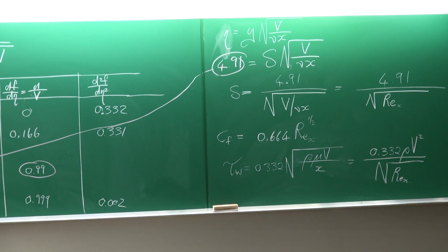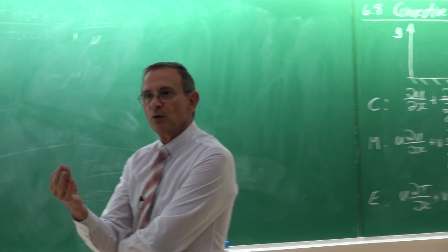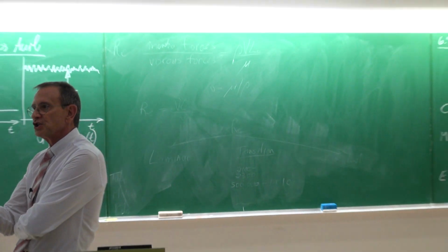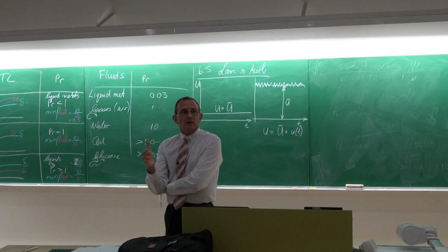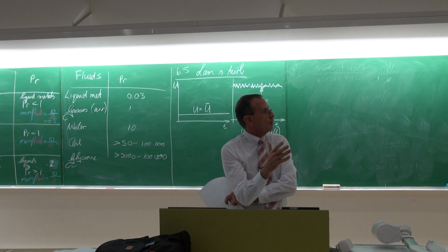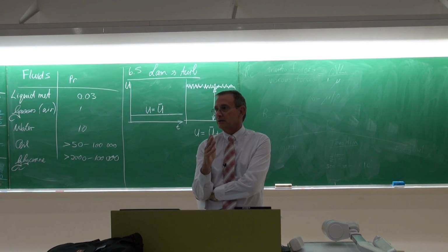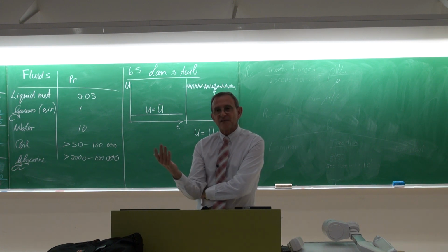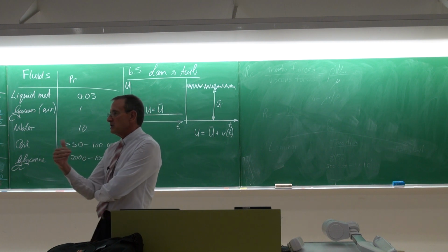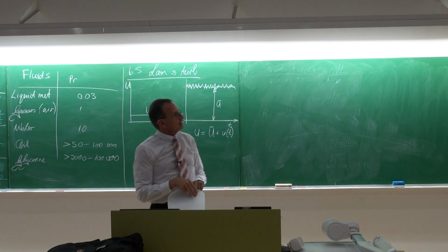And you can use this to estimate approximately the thermal boundary layer thickness, and from the thermal boundary layer thickness you can get the skin friction and the shear stresses on the material. So in the early days of aerodynamics, that is how airplanes were designed. The fuselage of an airplane also was considered as a flat plate. The curvature is very small in comparison with the total length, and that was actually not too bad